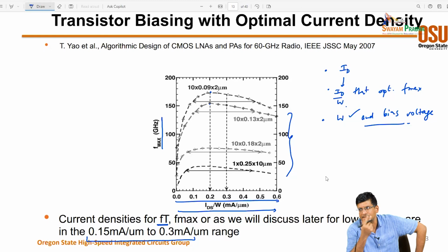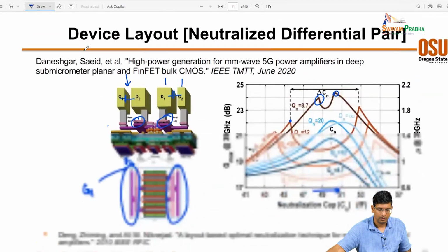So each metallization in CMOS, I think the higher metals can take something like 10 milliamp per micron. So again, you might be limited in the sense that you want to make sure that your metals are thick enough and wide enough to handle the currents that are going through. But that's more about how many fingers you pack and how tightly spaced, not a current density question still.